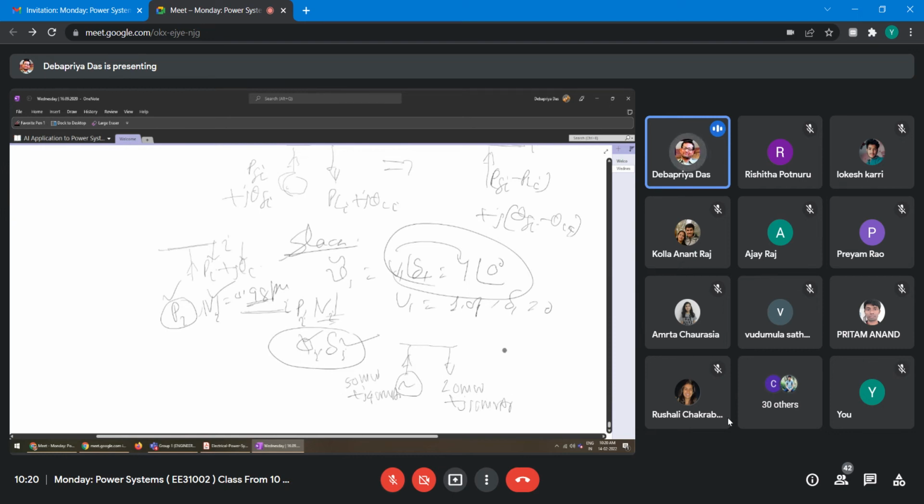So now, what is the net power injected at this bus? 50 megawatt is injected, and the load is this. So the net real power will be 30 megawatt, right? And what will be the reactive power? 40 minus 10, so 30 megavar. So this is the net power injection. And whenever we write it, suppose this is the ith bus, Pi we write as scheduled, that is known. This is your Pi scheduled. Similarly, Qi is also equal to 30 here.